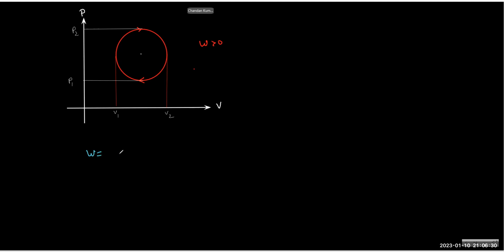So you cannot write pi r square, you have to write pi Rx Ry. A radius from the x-axis and a radius from the y-axis. So the way of writing is pi, from the x we can write as (V2 minus V1) by 2, and from y we can write (P2 minus P1) by 2. So that is why I said this is a very standard problem. You must know this answer. To keep the dimension of the work intact, you have to take a radius from both axes once, right? Yes. It is clear, guys.